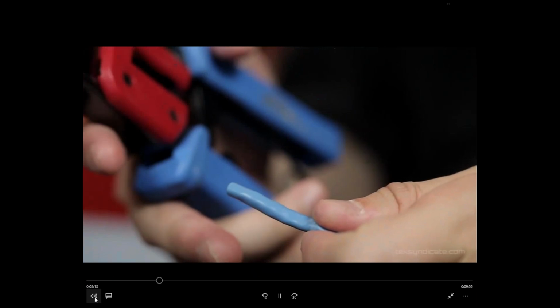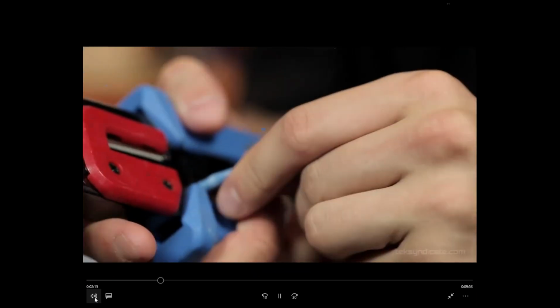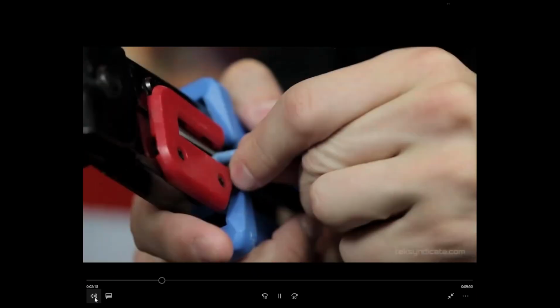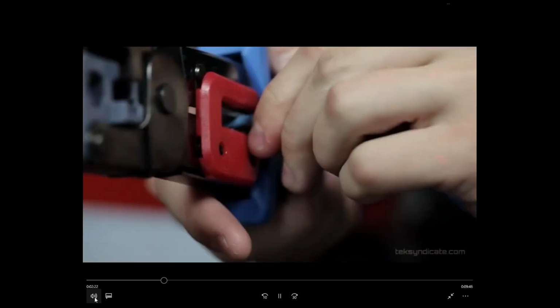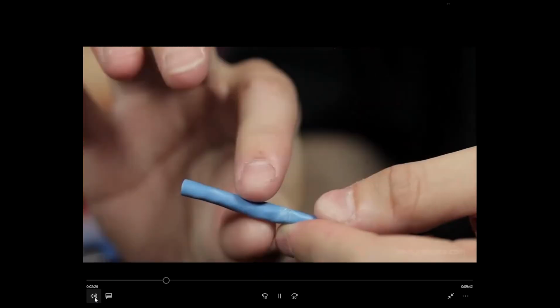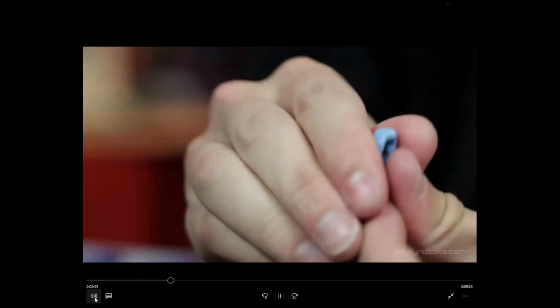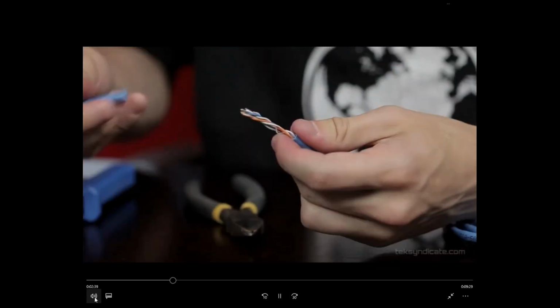So we want to scar the cable sheath so we can break away the sheath and expose our conductors on the inside. So we're going to use it very gently. We're going to scar the cable sheath with the cutter there. And now we're just going to bend the cable, and you can see the real stress here. You can bend it, and you can put some stress on it, and it'll break away. Alright. Get the sheath exposed.